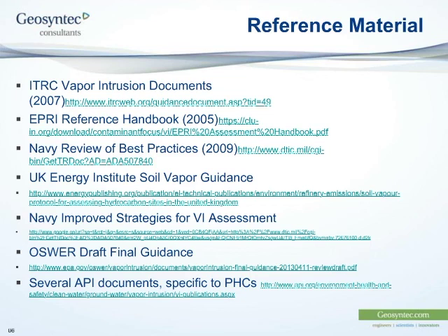Furthermore, rather than saying the word heterogeneity, I think what I'd rather use is the word stratification. So in cases where there are laterally continuous clay-rich layers, they can act as a very effective barrier. And they don't even have to be very thick in order to be able to do that, as long as they're continuous.